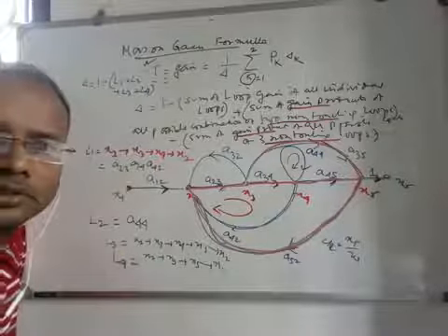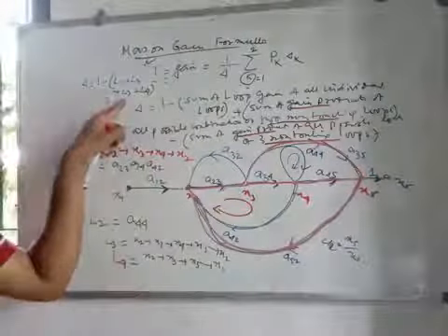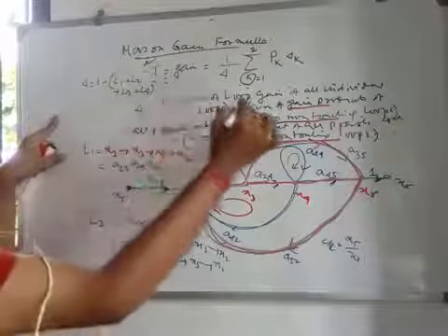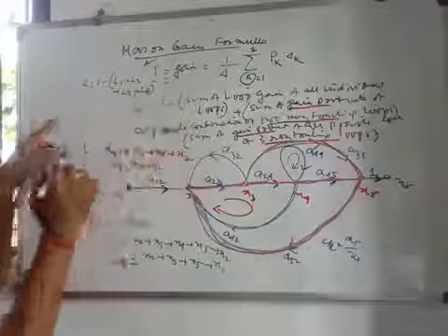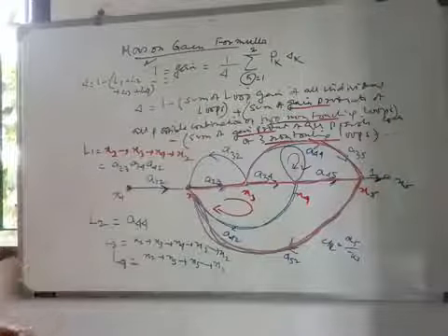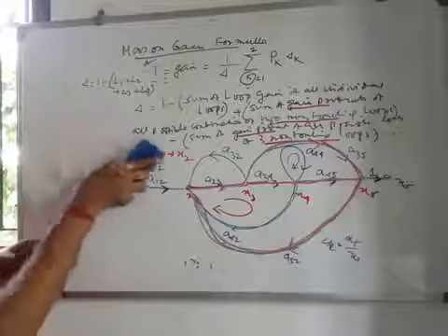So you see this L3 and L4. So this is up to this second term. Now, sum of gain products of all possible combinations of two non-touching loops. So that is very much important. Two non-touching loops. What is the concept of two non-touching loops?